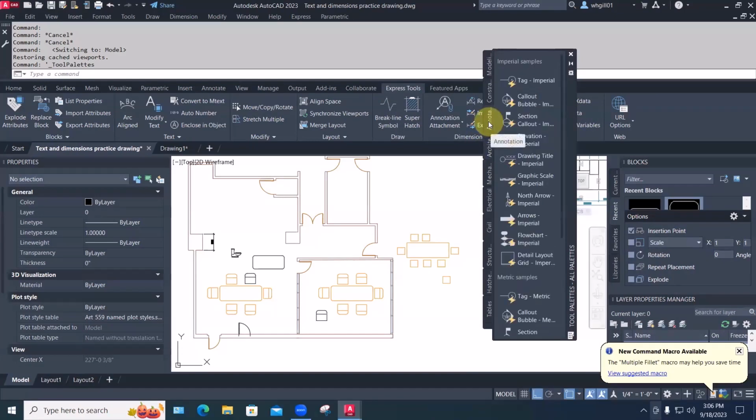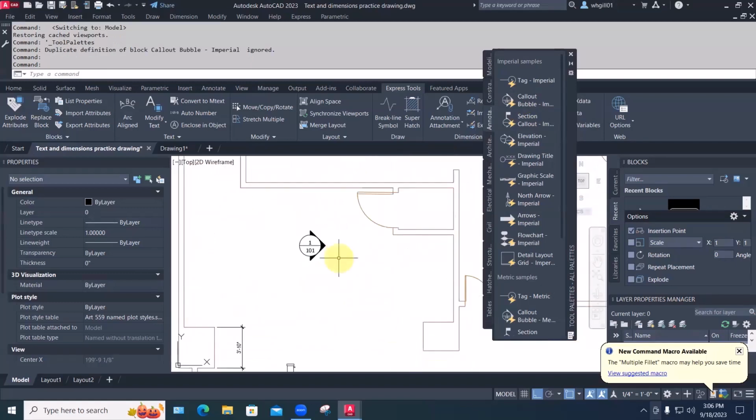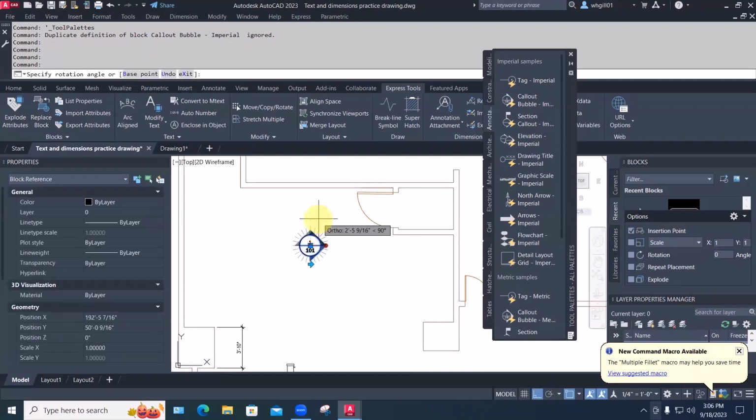And what we're doing is putting in the marker that says, looking at that wall, that's going to be, let's say, detail number 1 on the given sheet. So this is basically a call out bubble, is what we're calling this. And we can just drag it right into the drawing. What we want to do is aim this arrow at this wall. With this particular semi-automated block, we can select it and then just drag it around so it's aiming up.